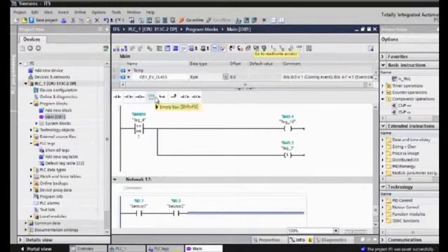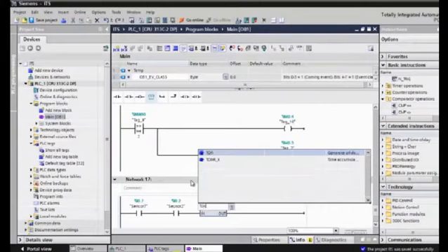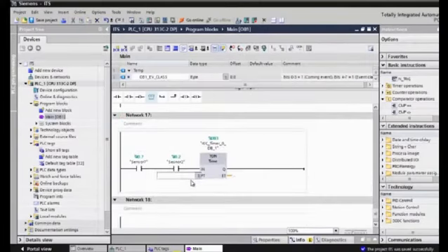But we need to make sure, so we are going to use a safety timer at this position. This timer T#1 second. We need to make sure we are at the start position, so we are going to use the continuous marker M0.0 and use set for Q0.3, or the mat.